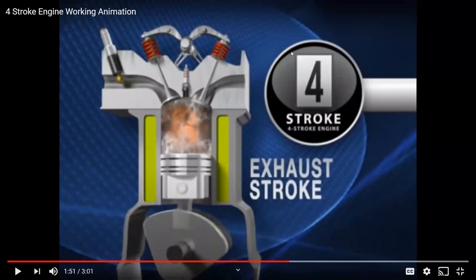So we're actually exchanging used up fuel and air for a new fuel-air mixture. But remember, nitrogen is nitrogen. You can't distinguish one nitrogen molecule from another. And since this whole thing is cyclic and the volume of the cylinder isn't changing, each time we're drawing in the same amount of air and fuel. So what you can do is just pretend that the new fuel and air is the old fuel and air, but it's now at a lower temperature and lower pressure.